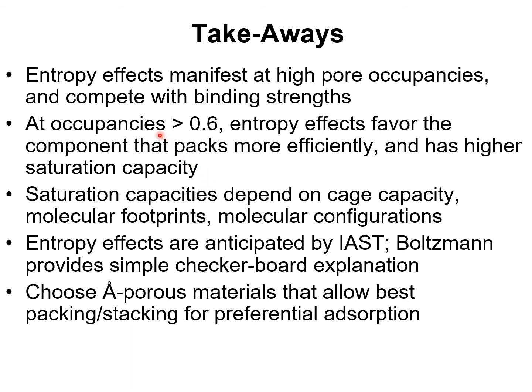Typically, entropy effects manifest at pore occupancies larger than about 0.6 and favor the component that packs more efficiently and therefore has the higher saturation capacities.